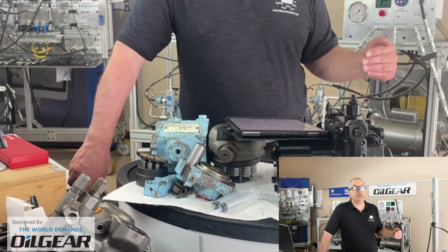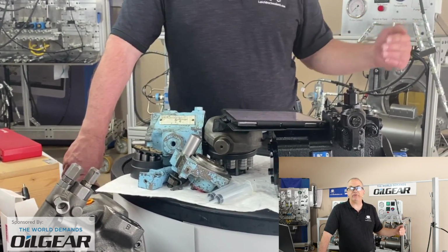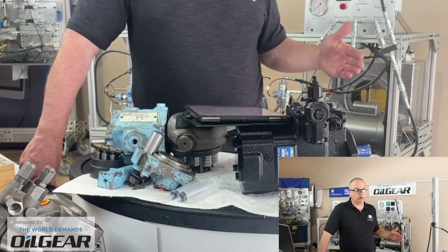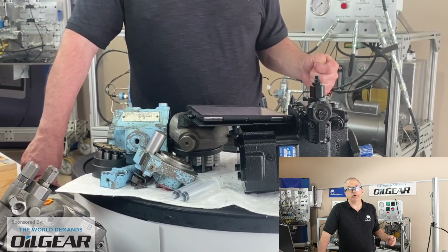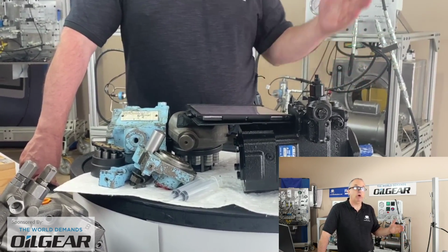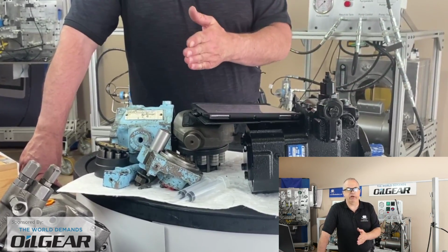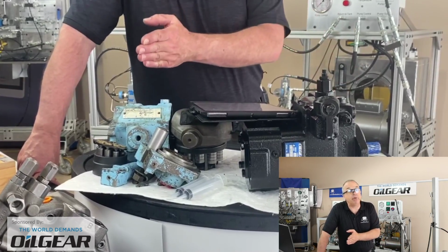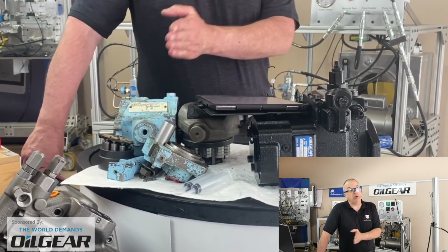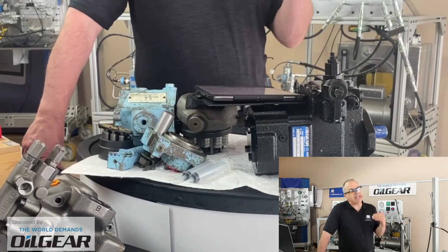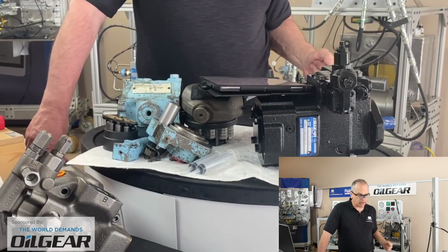The fastest thing we could do in a service condition, in a coffee break between work cycles, was to take the smaller hose off the case drain line and measure, and we found that a badly overheating pump had an extremely high value on the case drain, much higher than the pump data sheet said it should ever be. So yes, it can be a clue, but not always easy.